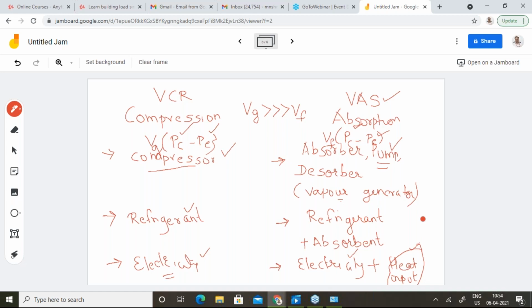We find by experience that in most places, the vapor compression system is widely used because of the obvious advantages of lower initial cost and higher coefficient of performance, whereas the vapor absorption system does have a market. If you do a Google search and look for the absorption chillers which are being manufactured, you will find that they are commercially available and widely used, in places where we have waste heat energy. Okay, so both are mature technologies and both have a niche market of their own, and both are viable technologies in their own areas, right?